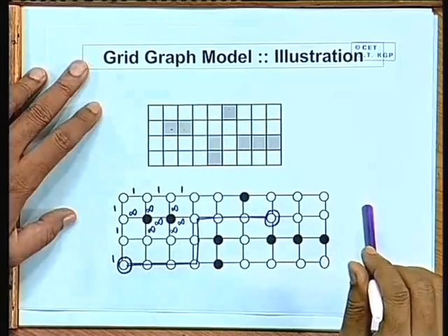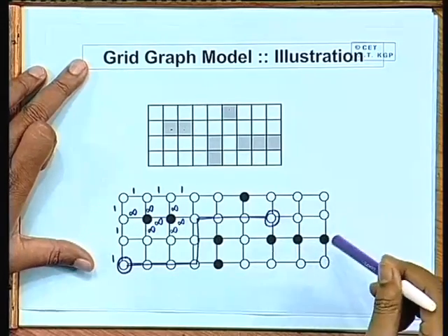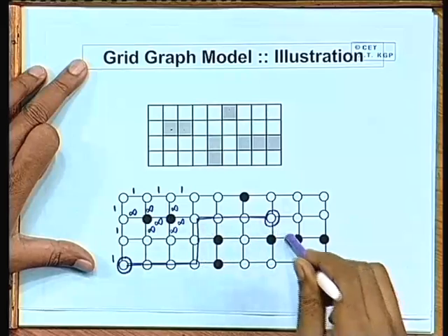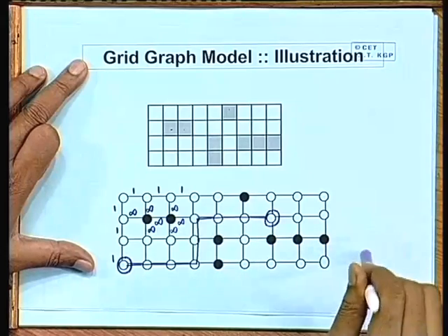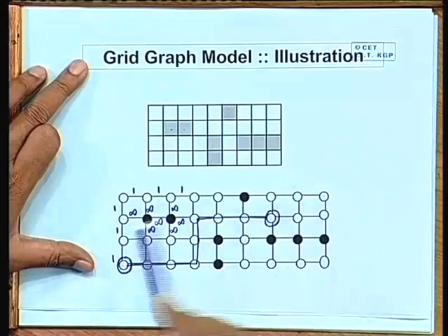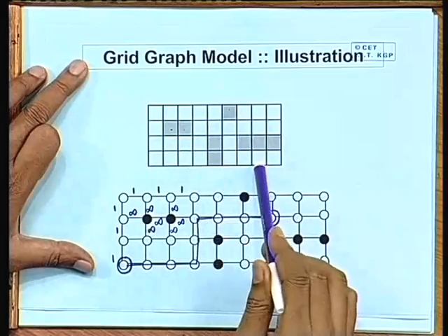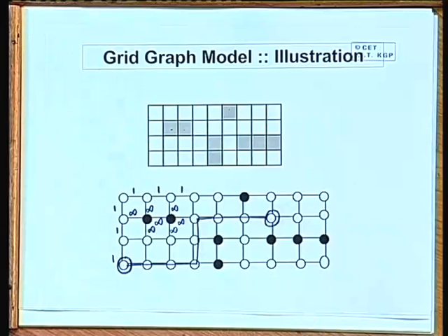So, the grid graph model and the approach I have just mentioned are suitable for finding a path, like Lee's algorithm, but not really suitable for global routing, because in global routing you seldom represent the problem in the form of grids at this resolution. But in fact, these methods have some utility. At some stage of routing you will find that the conventional routers are failing to find a path, then you will have to revert back to methods like this, which will find a path if it exists.